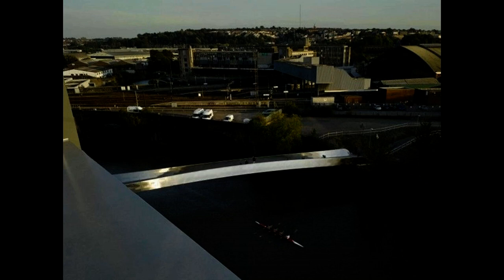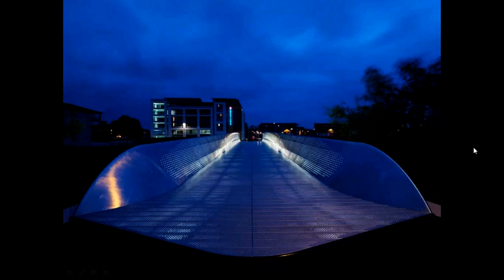M-E-A-D-S Reach Bridge. The architects said, we want something that's almost completely see-through. You know, could we make it out of glass? Could we make it out of perspex? Make it almost invisible. And the engineers said, well, yeah, it's possible, but there's a slightly different approach you can take. You want something very lightweight that you can build off-site and lift into place, right? You don't want to have to disrupt anything. You want a very easy construction process. So what they suggested was to make it out of aluminium and perforate the aluminium.